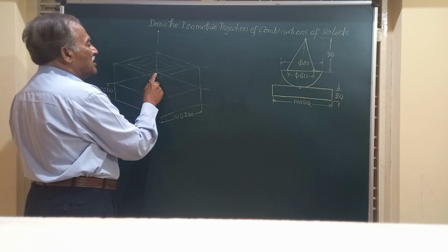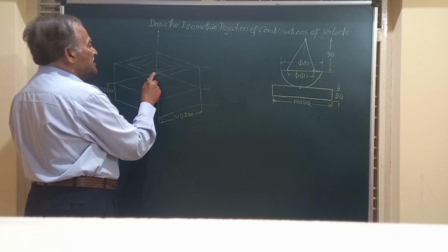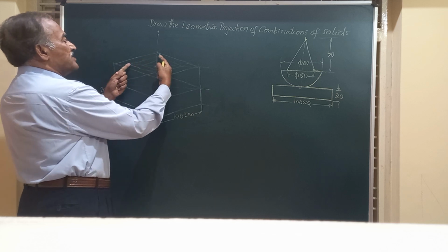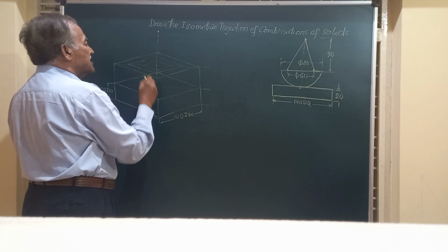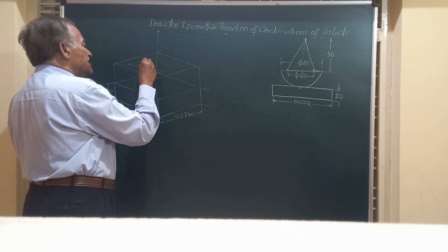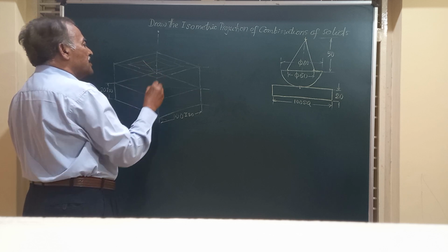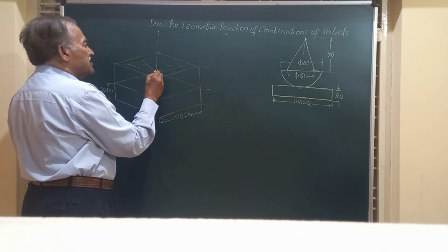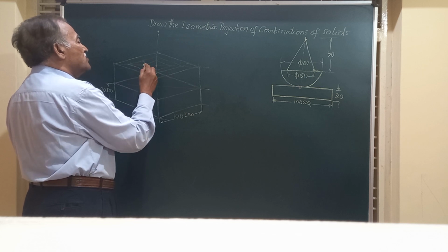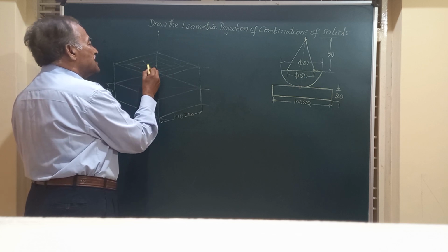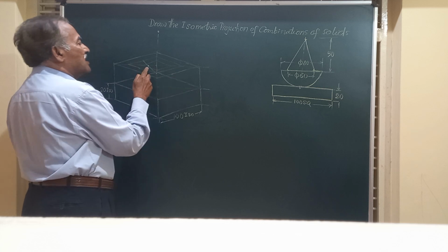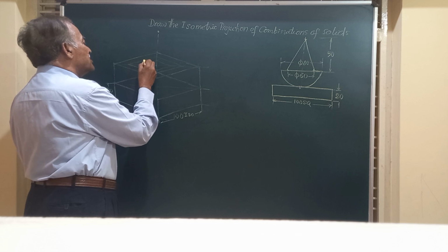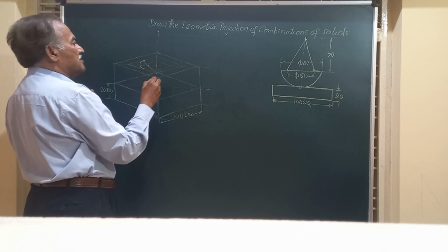I will take this one end of the parallelogram as a center and join that to the opposite side center. Opposite side is this length, and I am going to take this center there, join to this. Please listen carefully, and it's so easy. Friends, when you join this corner or point 1 with this, you see this cutting the horizontal diagonal at center 1. So with center 1 and radius equal to this much, I am going to draw an arc.